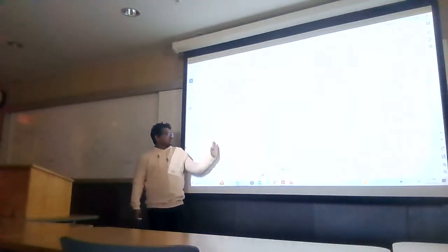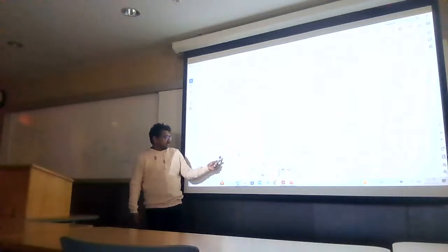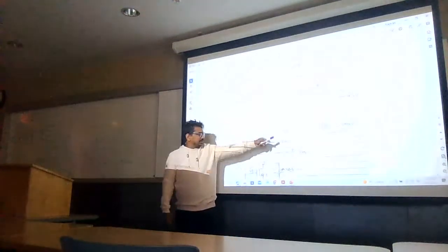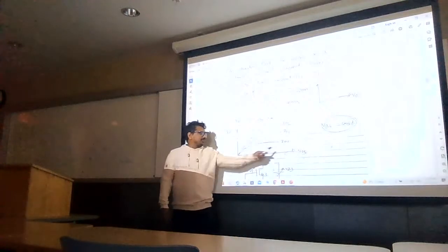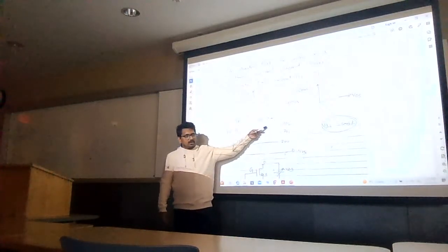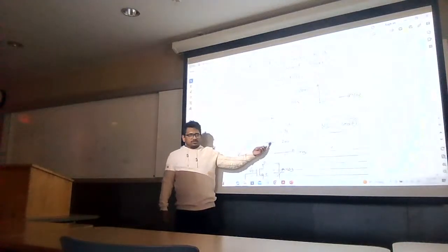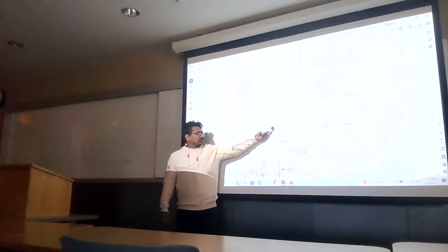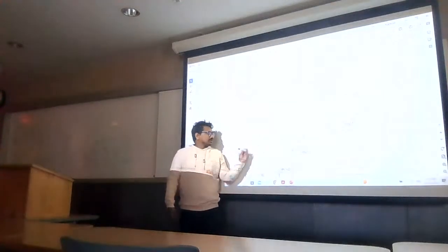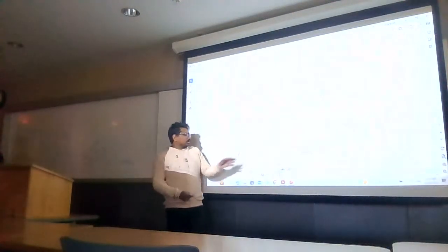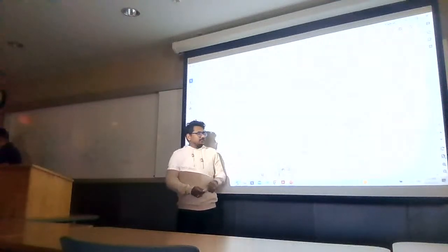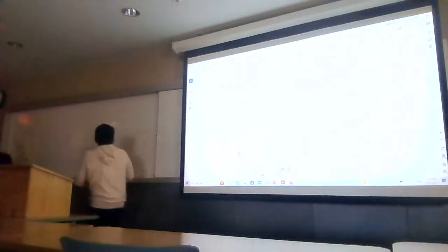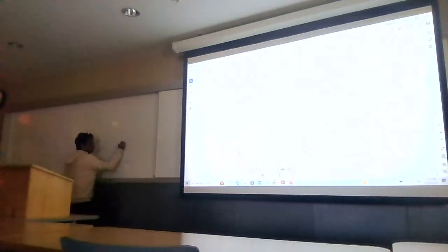Okay, this is just separating the operating conditions. Let's say here my VGS is constant, and if I increase the VDS, definitely it increases my current. Let's say here VDS is 1 volt, here VDS is 2 volt, and here VDS is 3 volt. If I increase the drain voltage, my current also increases, and my saturation point also moves like this. If I increase my VDS, it will go like this, and my saturation point also goes like this.